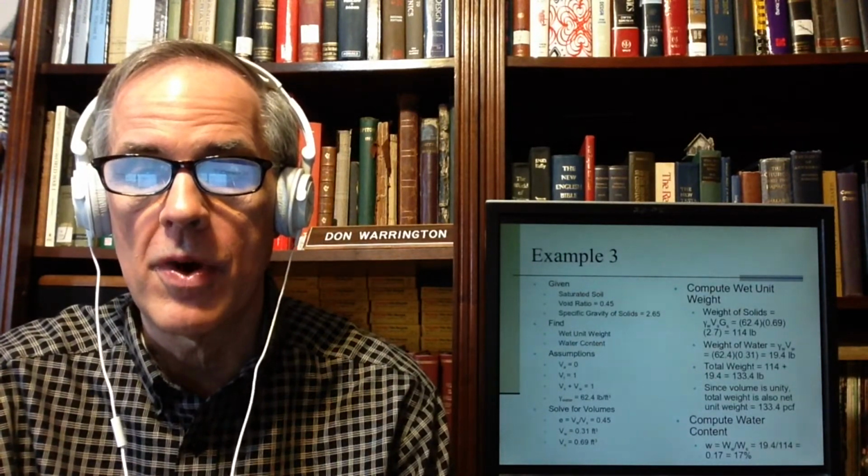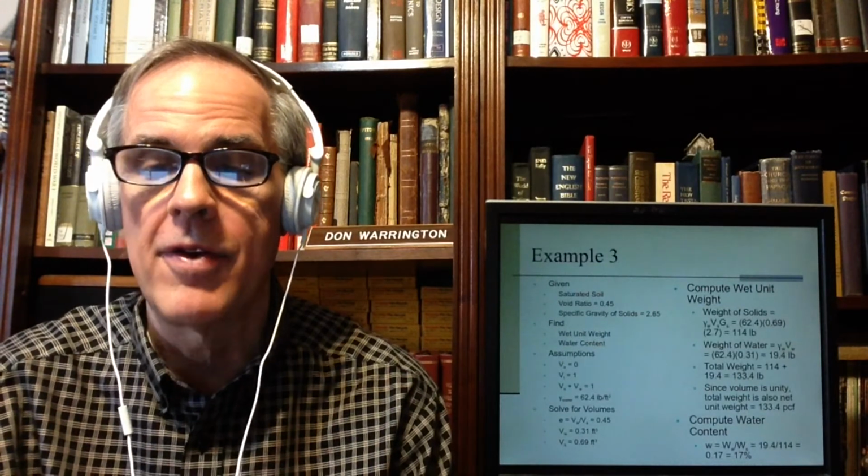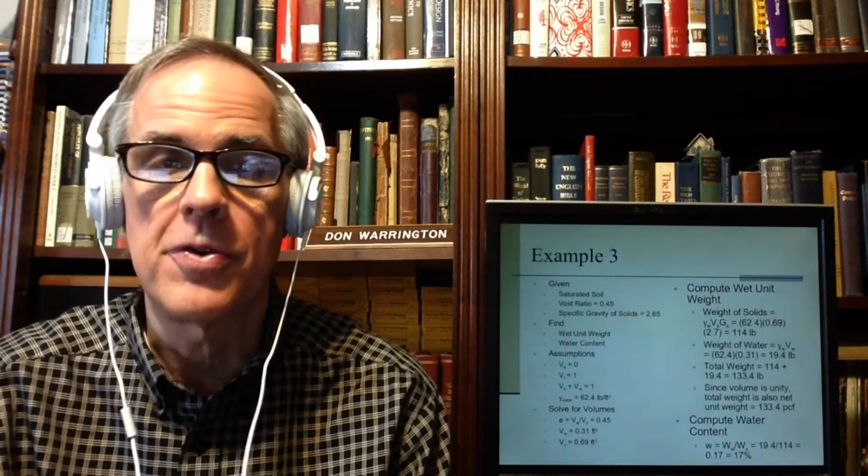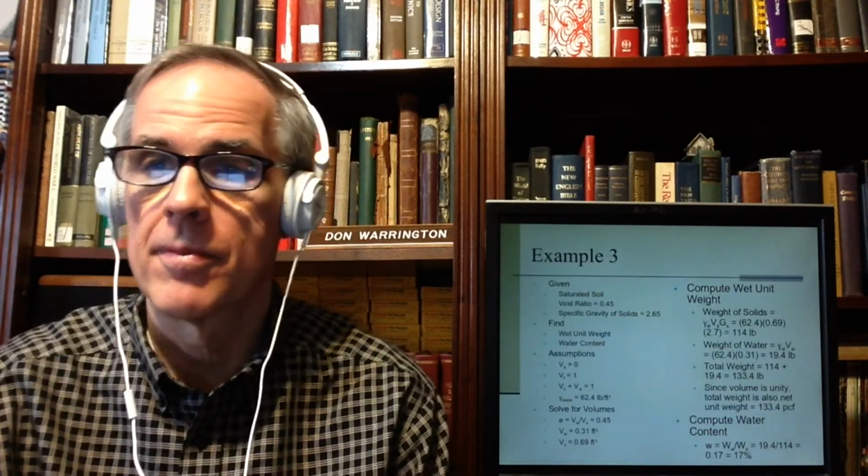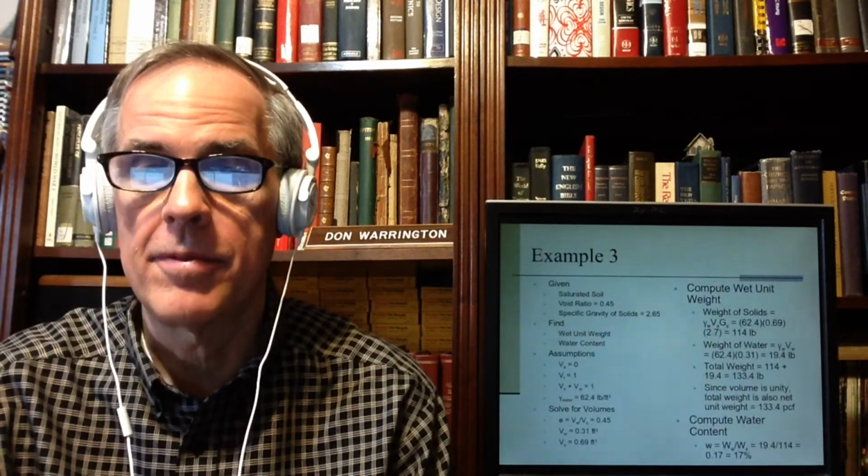And then I turn around and compute the water content. Now that I have both the weight of the water and the weight of the solids, I just divide the two and I get a water content of 17%. And I'm done.